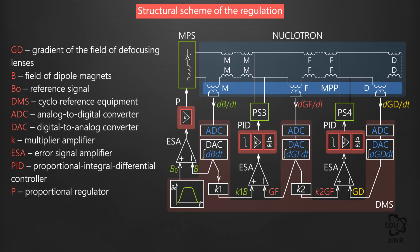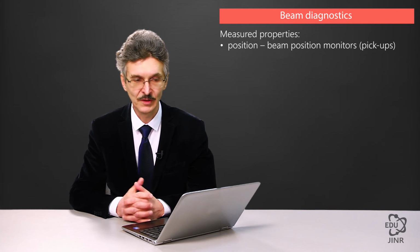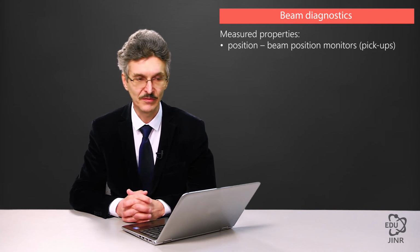On the operator's screen, there is a special window on the control panel where a reference function can be specified. From here, one can see magnetic field signals in dipole magnets and quadrupole lenses, the voltage and the current of all the power sources. After a cycle is adjusted, it is possible to inject a beam.